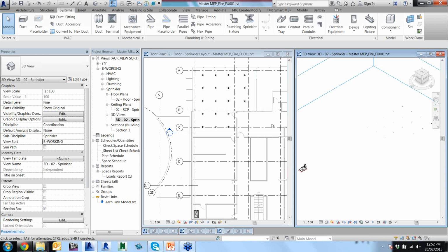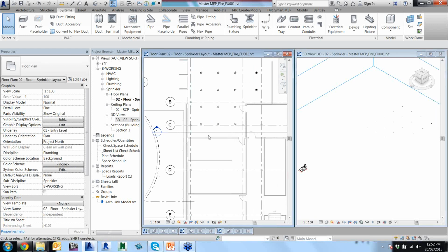But what I've done here is a good way of working, to be honest, especially with fire and fire pipe layouts. A good way is to not only have your floor plan view open, but have a 3D view open, and for that matter, even if you've got a section view, you might have that open as well. Tile them out like this, and then as you work through this demonstration you'll actually see it routing in a 3D view, and you can see what's going on. It allows you to really see what's happening and make sure that elements are placing where you would expect them to, especially on the elevation side of things, that things are not sitting on the floor or too low, for example.